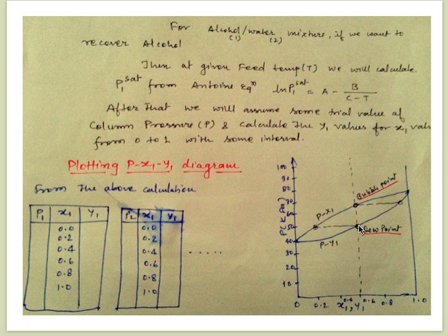Similarly for dew point we know the vapor composition. So if we draw here, correspondingly we can check, because this point is on the liquid line, it will give the liquid fraction. This point is on the vapor line, so this will give the vapor fraction. So similarly you can read x1 and y1, because if you are reading something from this line, you will read y1 here, and if you are reading something from this line, you will read x1 from this one, because both x1 and y1 are plotted on this x horizontal line.